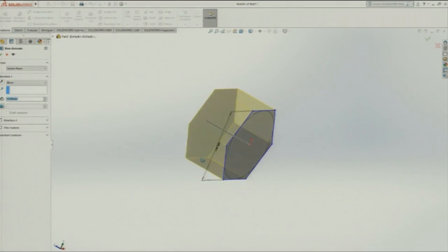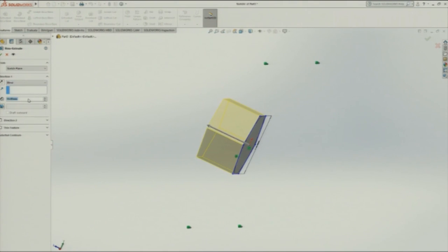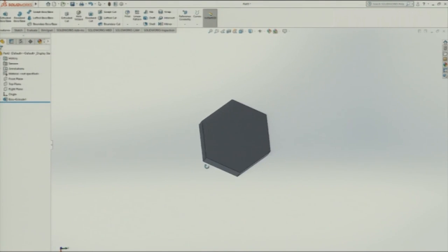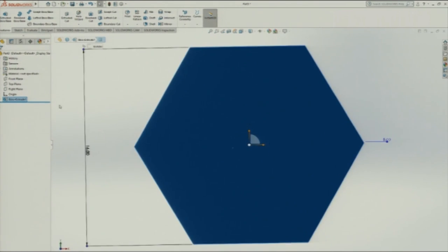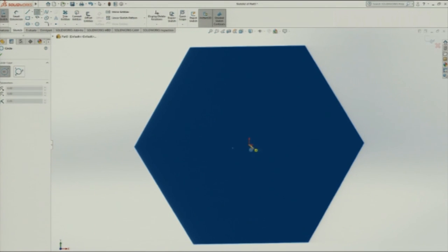So, let me extrude it. This is extruded to size 10, which is a little smaller, 5 would be lower, I can put 8 mm, that is okay. So, this is the base for my nut. I need to now put again the similar operations.